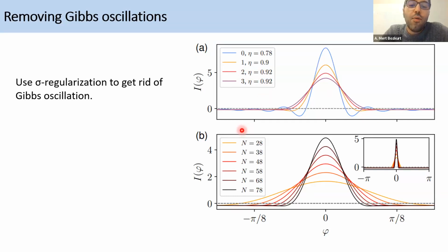And furthermore, one can also check that you can get higher and higher efficiency if you have more and more arms. You can understand this as follows. If you have more and more arms, it is much, much easier to fit a function using the Fourier coefficients of single arms. So therefore, if you were to have, let's say, an infinite number of arms, then you would get an ideal diode.